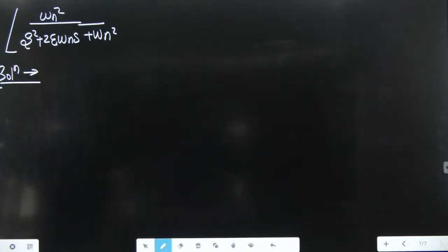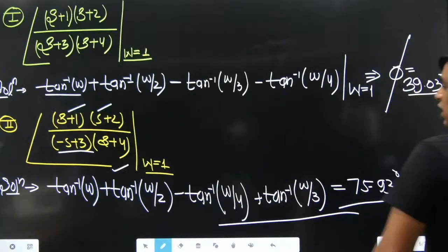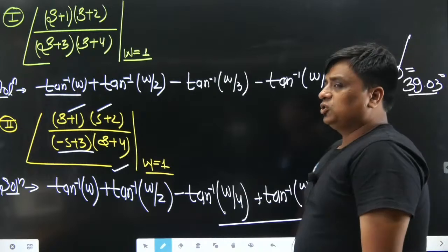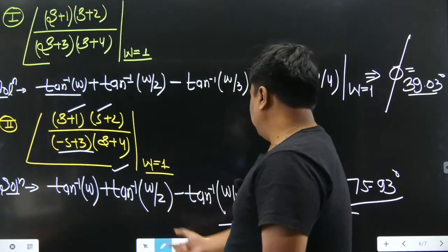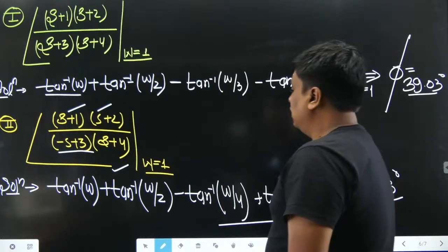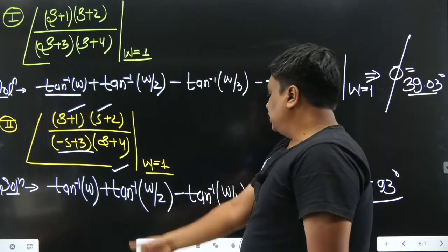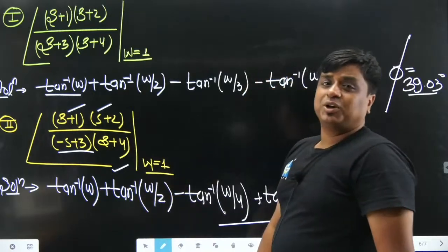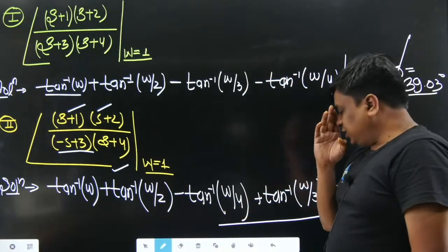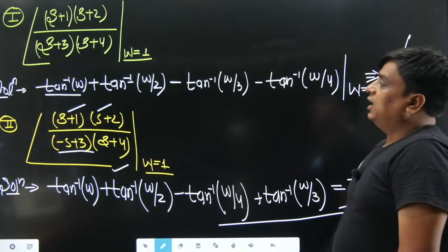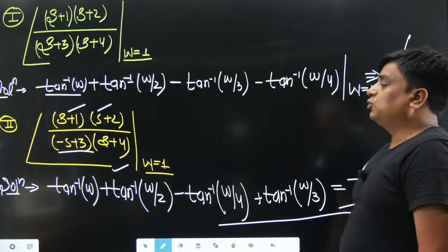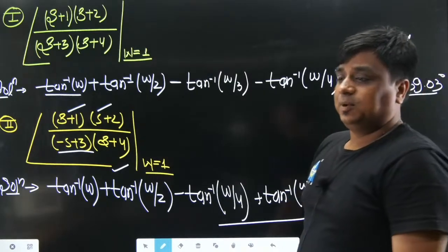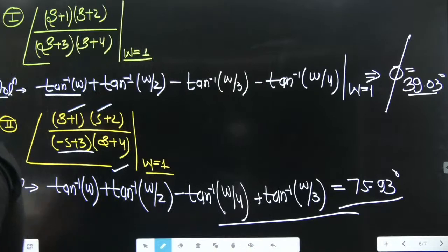That's quite easy. How do we locate the infinity angle in the s plane? What does infinity mean? Obviously your omega must be going towards a very large value. If omega goes to a very large value, one term becomes pi by 2 and the other becomes minus pi by 2. Put together, the pi by 2 terms add up, so the angle at the highest value of omega is simply going to be 180 degrees.